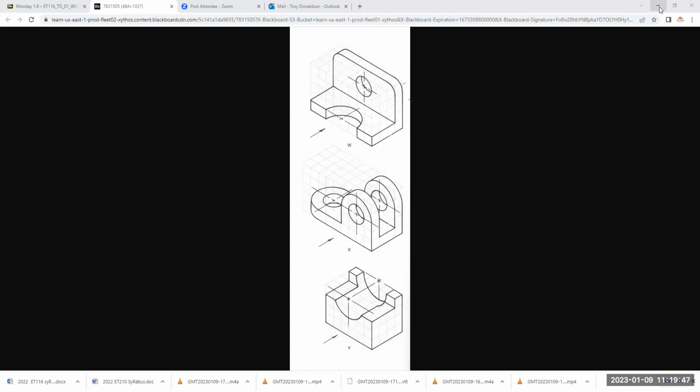So in this view, we can be in either paper or model. They're the same. Like this is model, where we draw the model. This is paper, but I can go back and forth. So if I click that, now I'm working kind of through the paper into the model. That's kind of the best way to describe it. Like it cuts a hole in the paper and now I can work in the model space.